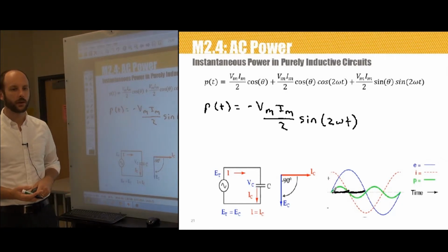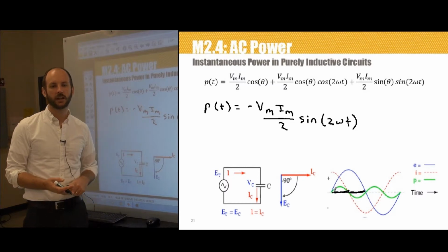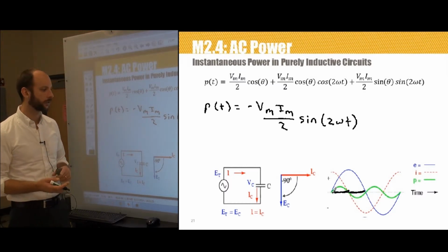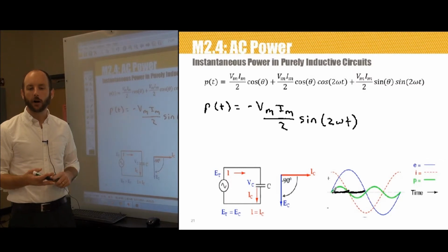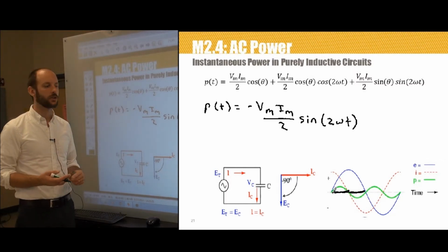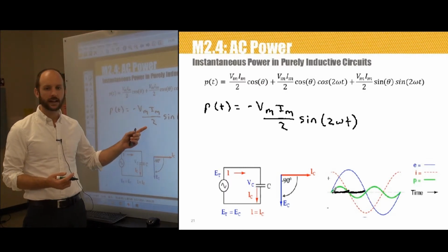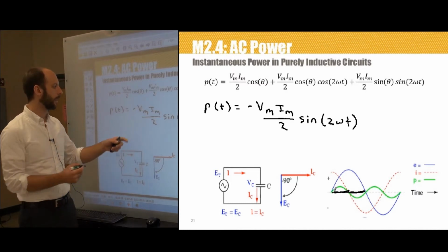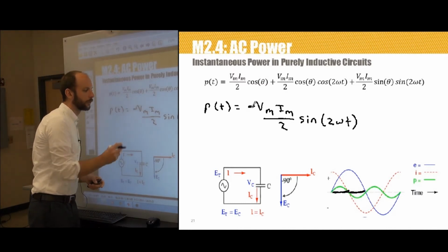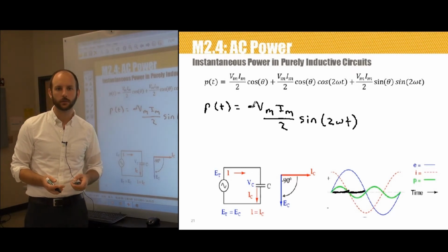We'll note that the Q term here is positive for inductors and negative for capacitors. That's just because we've got a negative term here. It's often colloquially stated that inductors absorb what we call reactive power, and capacitors deliver reactive power. Deliver meaning there's a minus sign in how much reactive power is actually being consumed here.